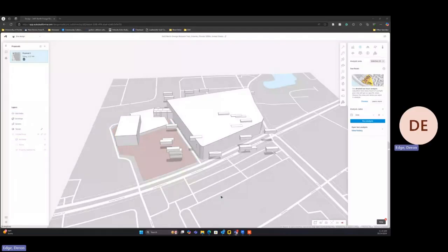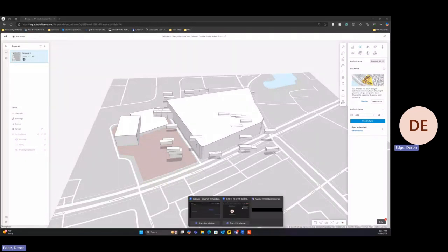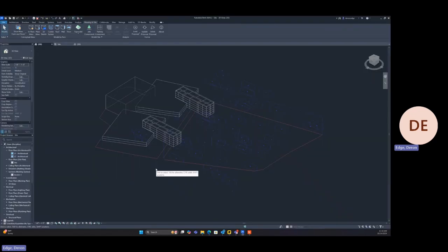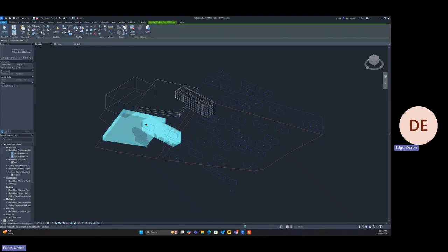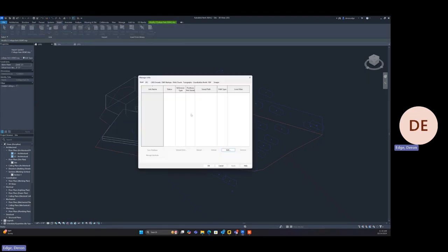Okay, I do want to make one additional note. Earlier, whenever I tested this, the TestFit file to Revit didn't come in Forma, and there's a reason behind that. Essentially, whenever you imported it as a link, manage links, it came in as SketchUp elements, and SketchUp elements were not compatible with going back into TestFit from Revit.